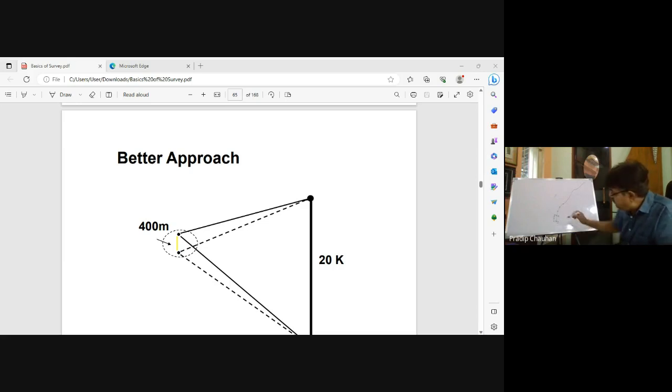Now we are using the total station, closing these towers, so that whatever inaccuracy is there, you are closing within a length of 5 kilometers. Similarly, this is another tower. It is known as a traverse survey using a total station. DGPS can also be used, but sometimes to get more detail, total station survey is preferred over DGPS. Control point is okay. Then next comes, after the traverse survey, the altitude, the height or level of that particular ground, which is very much important.